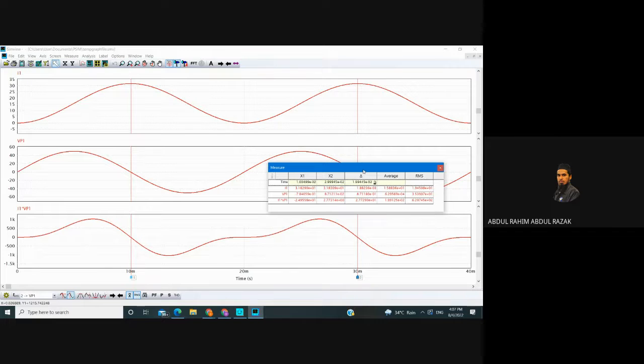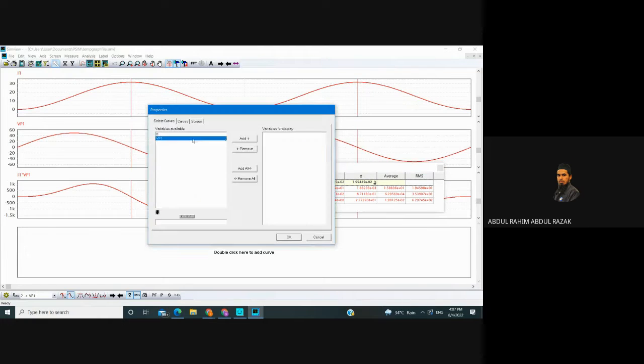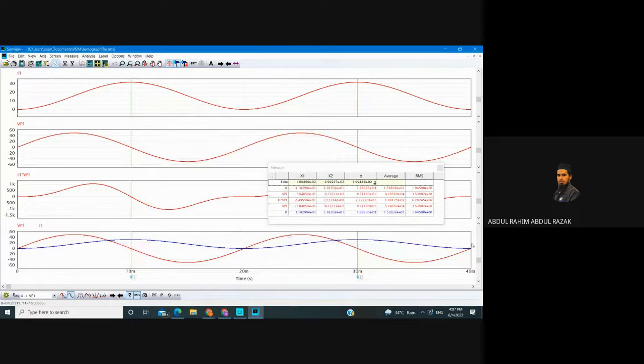So by right, if you want to show that kind of result or discussion, we should overlap the current and voltage on the same frame. Is that one screen, we put both curves together, then we can comment in terms of their lagging or leading. So we can put the measurement legend on the graph itself, where, how much, and the lagging or leading values.